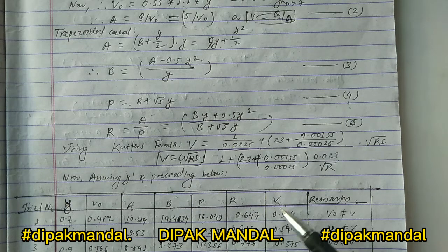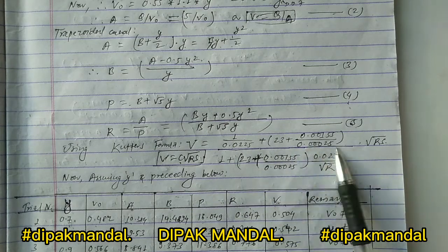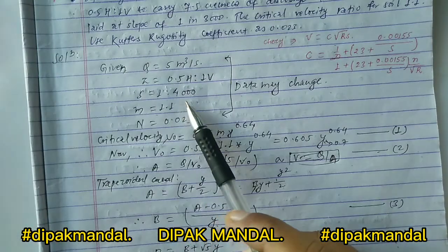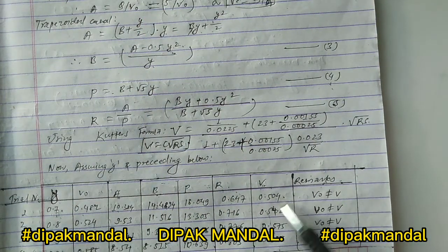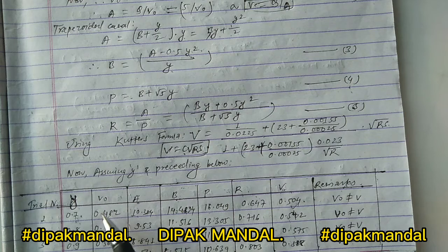Now we have to calculate the actual velocity, and the actual velocity is given by this equation. Okay, and simply we use this formula, root under RS. We already calculated the value of R, and we have S equal to 1 by 4000. So after putting all these values in this equation, we get the value of v equal to 0.504. Okay, so you can see here we have to compare the value of this v with this v naught. This is the actual velocity and this is the critical velocity. Okay, so you can see here these two values are not matching.